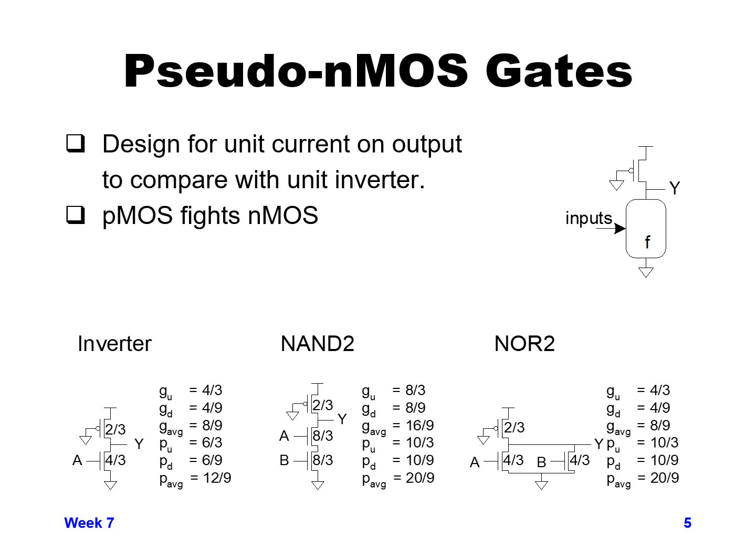And just be aware that the falling delay and logical effort is less than it normally would be for static CMOS, because you only have the input capacitance of the NMOS device and not the sum of the NMOS and PMOS devices on your inputs A and B. So the logical effort is going to be a lot smaller for pseudo NMOS, but again, keep in mind that the PMOS is fighting the NMOS, so you have a certain amount of static current always being drawn, and so it's going to be a higher power type of logic.